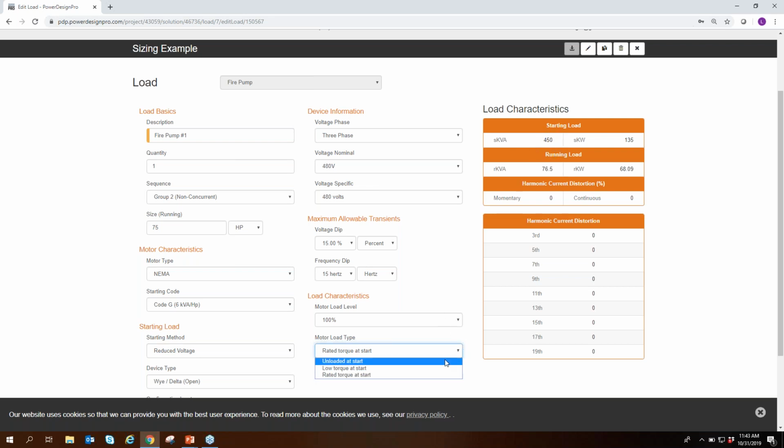We think a fire pump lives somewhere in between. It's low torque at start, but the torque builds as the motor accelerates. And at some point, the fire pump motor runs out of torque and has to make that transition. Hopefully, we give it a good 5, 6, 7 seconds to push as high in speed as it can and make that transition up at 75, 80% speed.